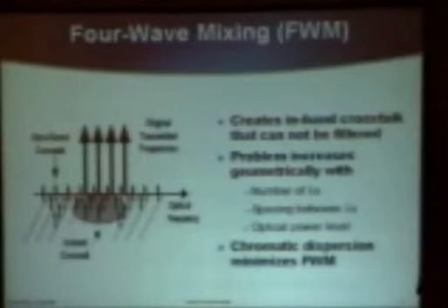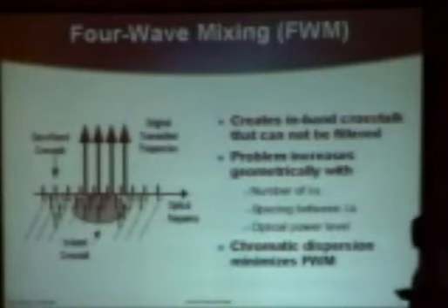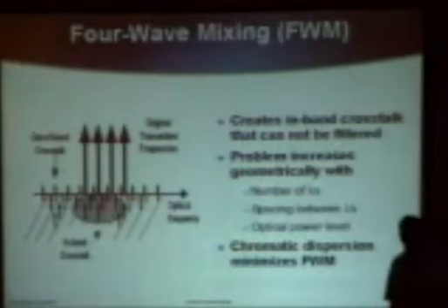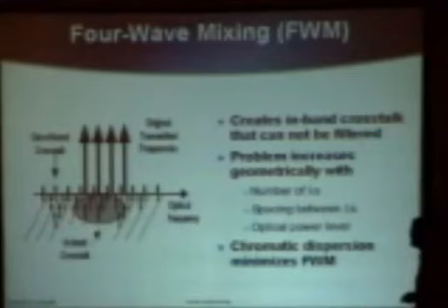And if there's not enough problems, just to show you some more, along comes WDM, which we're going to talk about in a minute. And the issue with WDM was, if there's no dispersion between the wavelengths, as in this case the four primary wavelengths travel down the fiber, they tend to interact with each other, and they create all these different beat signals. Think of it in terms of radios. It's the same thing. It's intermodulation distortion and beat patterns appearing.